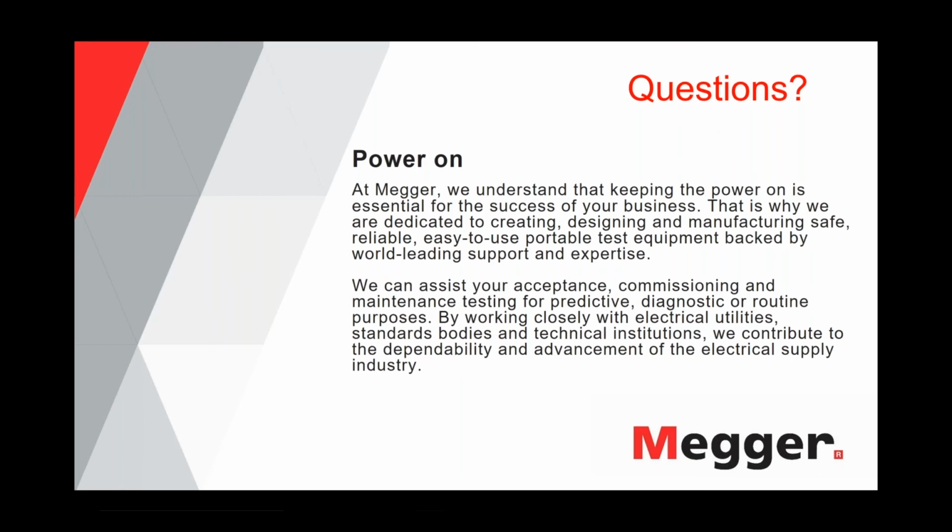Thanks, Robert. Henning, how do you assess a hybrid circuit? Well, I think Javier was alluding to that. Tan delta measures dielectric properties of the insulation, and the dielectric properties of different type insulations, most of the time when people have mixed cables like XLPE spliced together with paper cables, are very different.